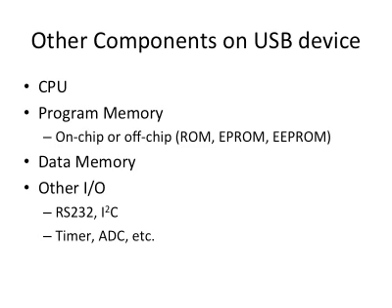Other components you may need on the USB device: other processors. If you have this USB controller as a part of the processor, then you will need to decide what are the functions you want to put on the major CPU. You may need program memory, ROM, EEPROM, etc. Data memory is probably needed as well. You may need other I/O interfaces depending on your application. You may have the need of RS-232 or I2C, or you need ADC to do some analog to digital conversion.